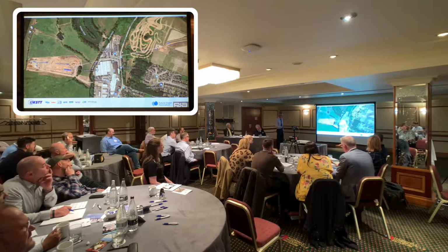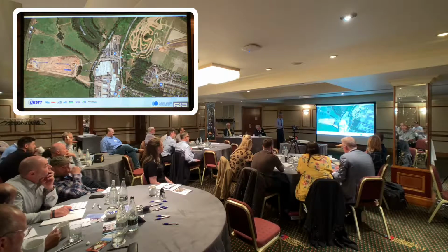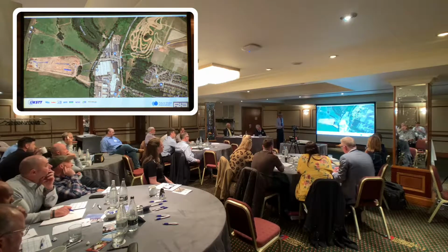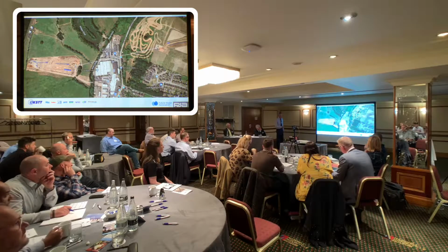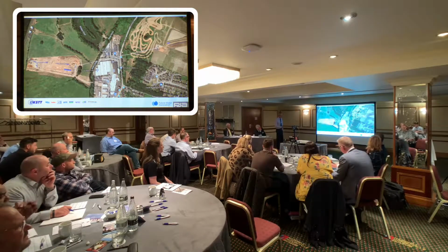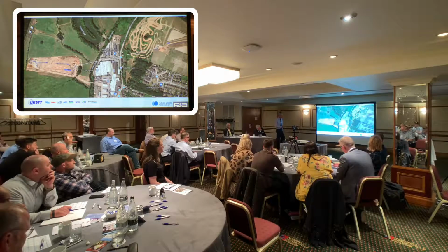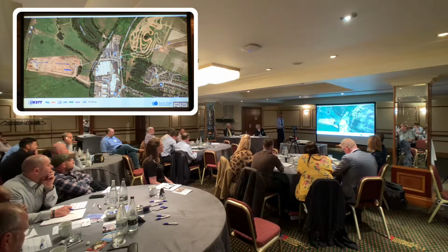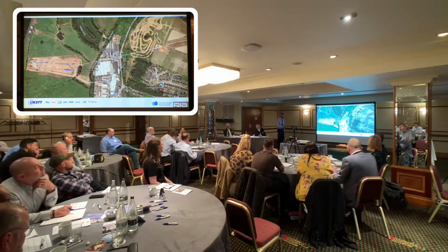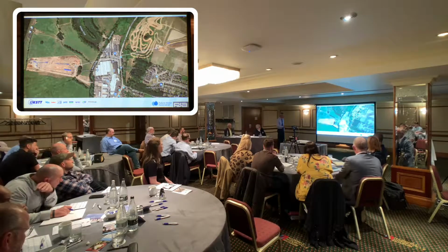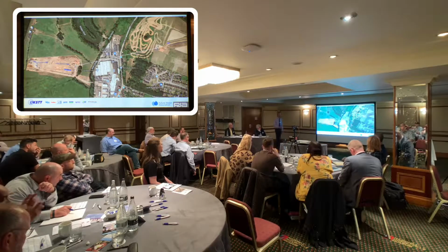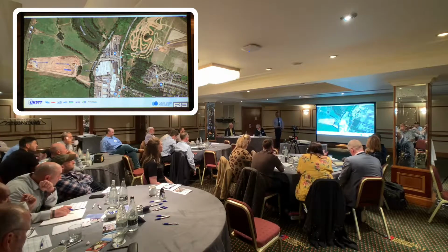And this is the drive shaft location. So because of where we are, there are no sewer disposal points for wastewater. The shaft is in sandstone with high water table. So we had to sink that shaft to, I think it was 35 metres deep as an underpinned structure with deep well dewatering to control the groundwater. These two holes here are the water lagoons that we had to put the water through before we could polish it with another system in order to get a discharge to river consent. So it's a particularly difficult site. And just illustrates some of the problems.